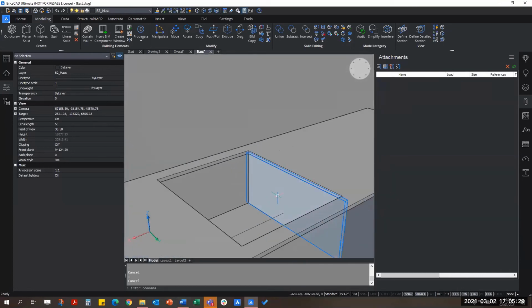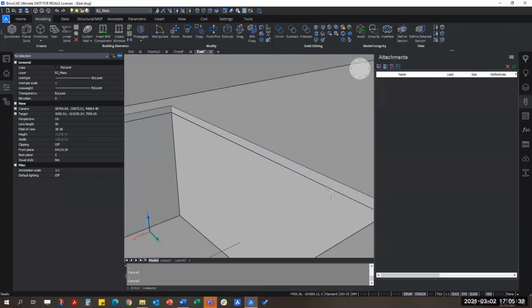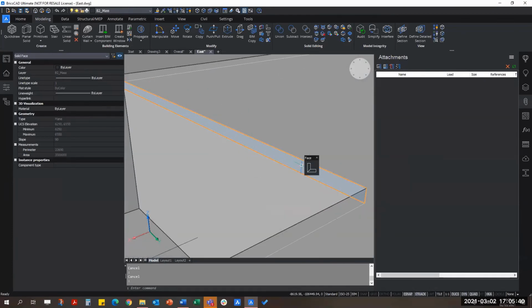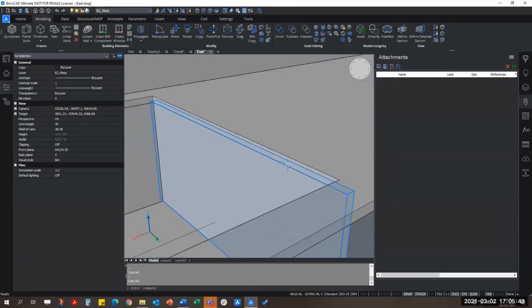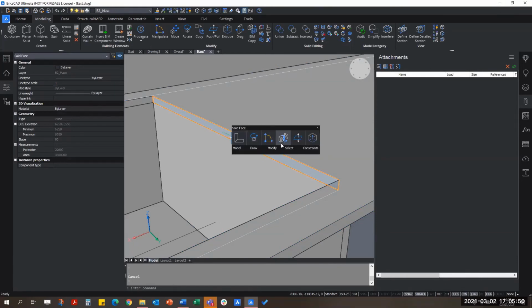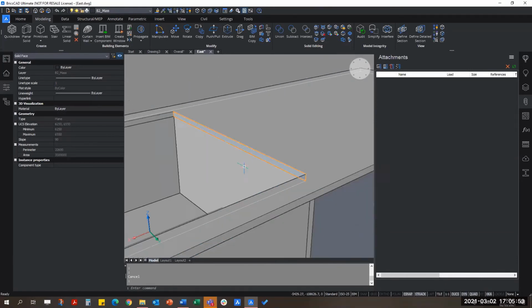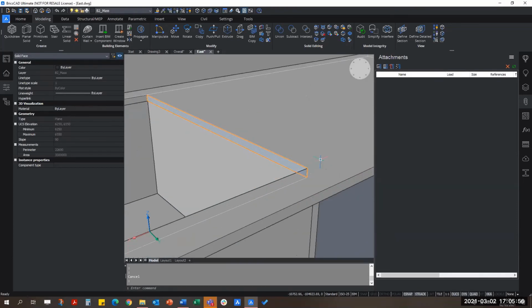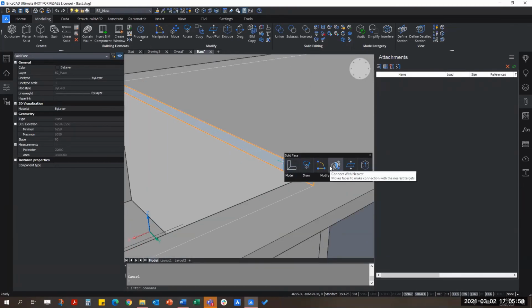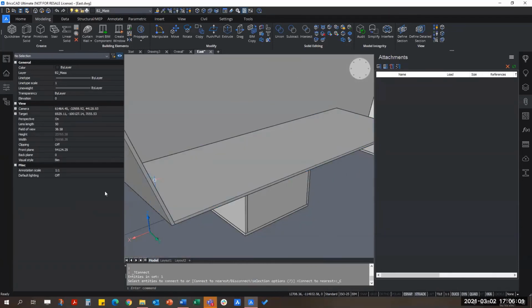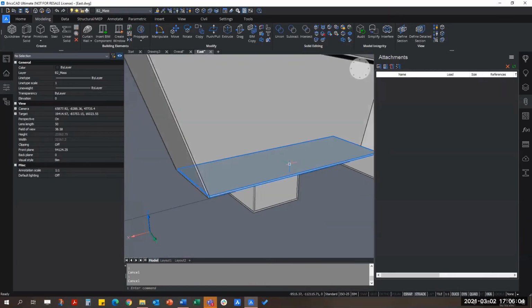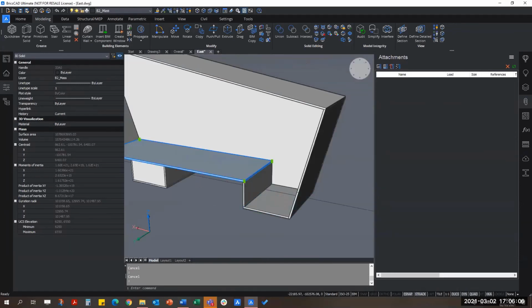Over on this side, you notice there is this big hole here, which I'd like to fill up. Well, one solution is obviously to go onto primitives, add a box of the same thickness, and union it. But we have another tool which is quite useful, called connect to nearest. I'm selecting this face over here, and I'm telling it to shoot to the nearest opposite edge in order to seal the hole. So if I do this connect with nearest, boom, immediately you find that the hole has been sealed and it's still one entity.